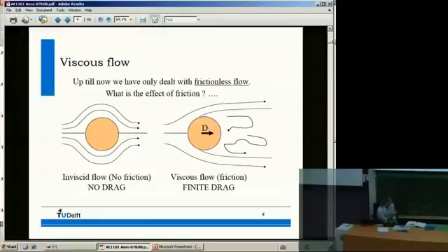And this drag force has a contribution due to the pressure difference over this object, because the pressure here is lower than here, so that's called pressure drag. And there is friction on the cylinder because the flow goes over the object and hits it. The flow speed is 0 at the object. Above there is a certain speed, so there's a friction force on the object. So that also has a certain force contribution, mainly in that direction.